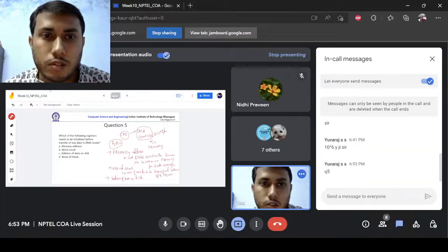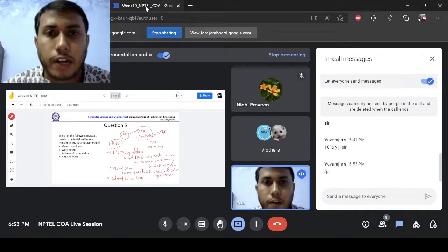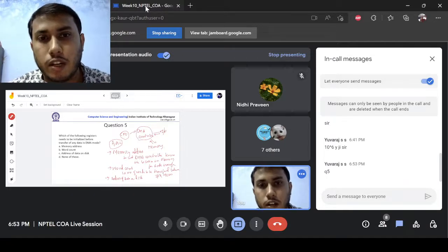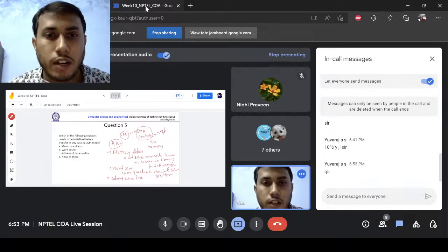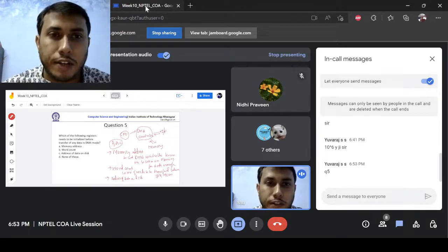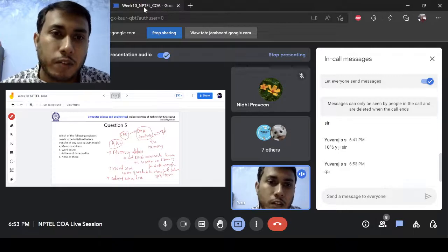Yeah, so if you have gone through the DMA controller lecture, you know what is the biggest benefit of DMA controller based data transfer mode. In DMA controller, the CPU hands off the entire data transfer proceedings to a special module called the DMA controller. This is the memory device and this is the IO device between which you need to transfer the data, and this is the amount of data you need to transfer.